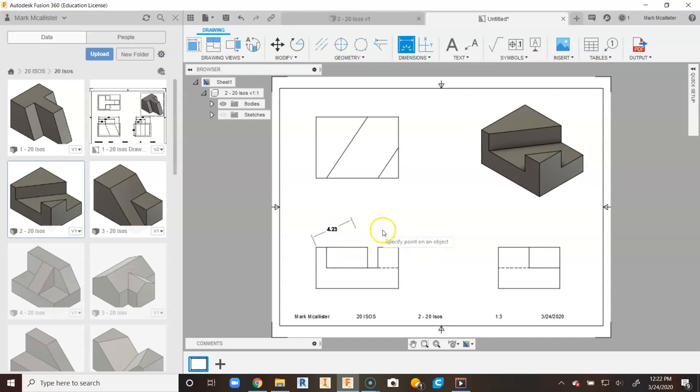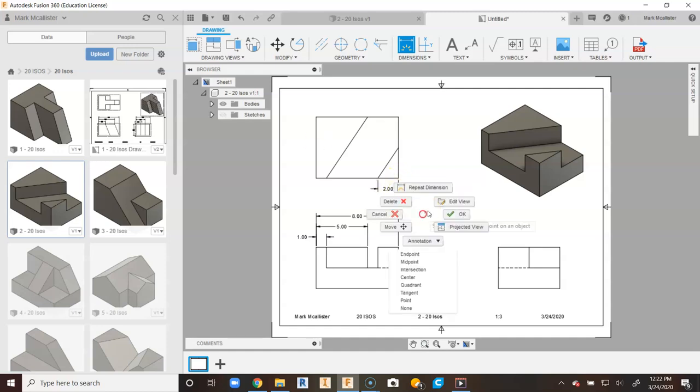Now instead of doing baseline dimensioning, we're just going to do normal dimensioning as we've done before. I see about 3 total dimensions we will need to do for the width dimension of the front view. So I'm going to drag each of these up here, and I'll drag that up and snap that into place. We don't necessarily have to do from here to here with this one. We could come up here and place that distance from here to here also if we needed to. I'm going to drag straight down and place that one up here.